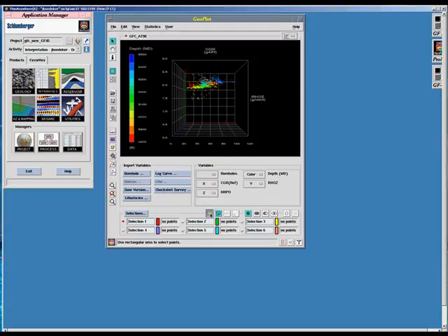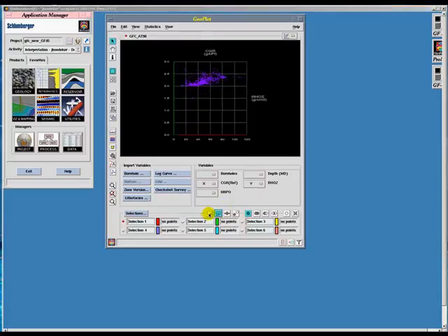The selection process works the same in 3D mode, but once the selection is made, the points are highlighted and the selection area rectangle or polygon is cleared. The selection area polygons are not presently saved in 3D mode and cannot be edited. Once the selection has been made, it can then be refined. This is accomplished by choosing any of the 6 selection modes: replace, add, remove, intersect, delete, and erase area polygon or rectangle.